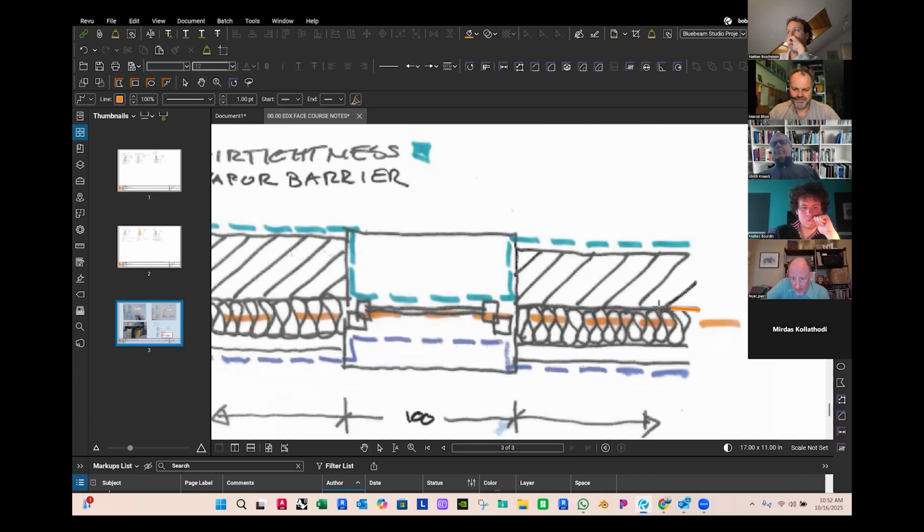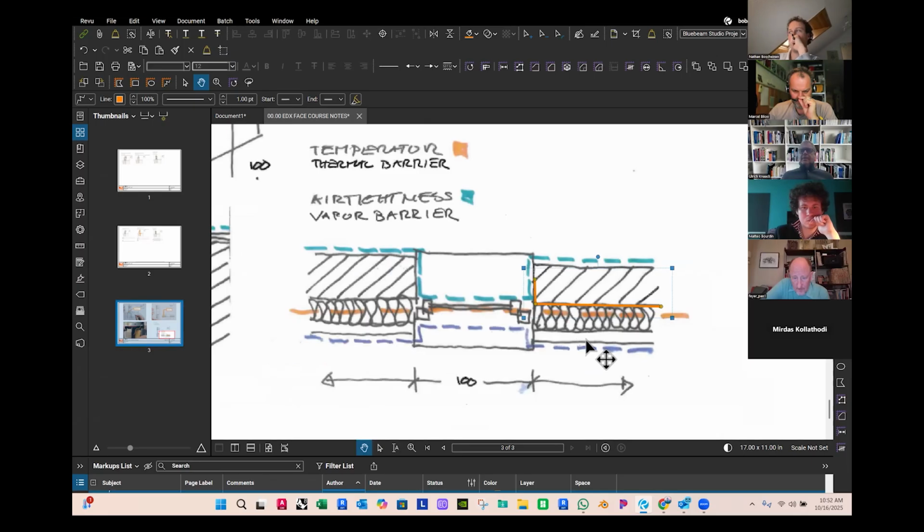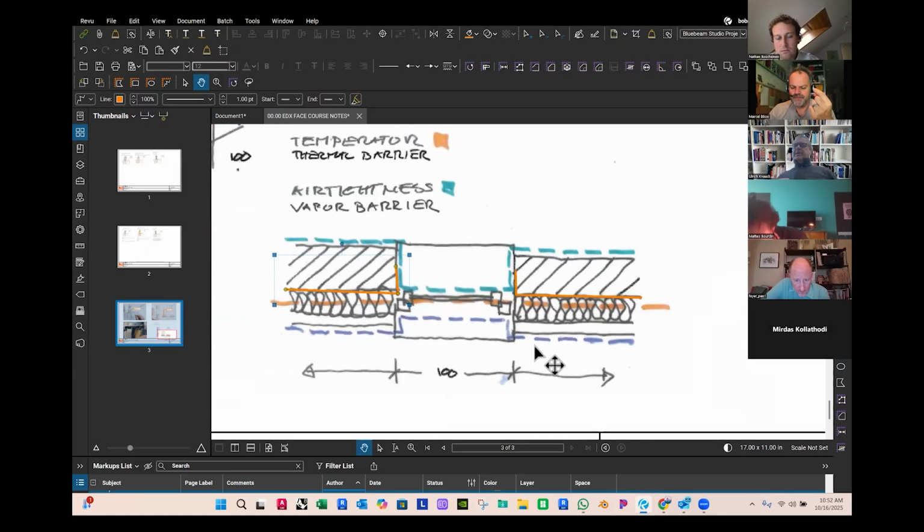I actually would worry about that. Yeah. Because humidity comes from inside, then penetrates your structure and stays in there. And the water from outside, you don't want to get into your structure, which means that then the vapor and water line is the same. It's actually at the outside, which means humidity gets in your entire structure, which I would not feel very comfortable with.